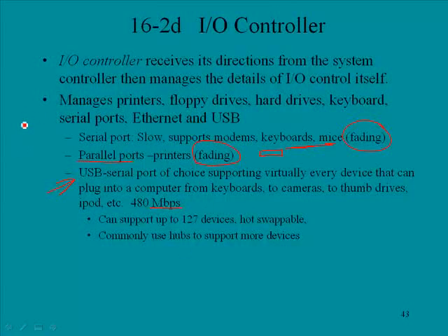The parallel port, remember we talked about parallel, you'd have the 8 lines, and parallel historically has been a faster interface because you can move 8 bits simultaneously. Serial is like when you have a modem connected to the phone and you're moving your data, but you're moving it over one wire at a time. But in recent years, great advances have been made in serial buses, which brought about the USB bus, and the USB bus is very fast.